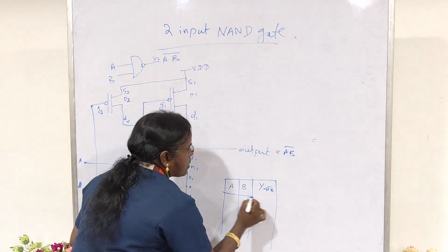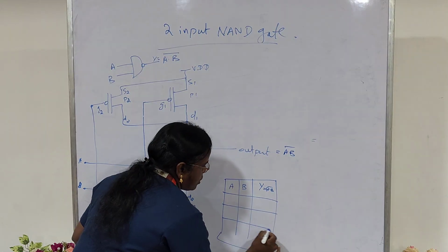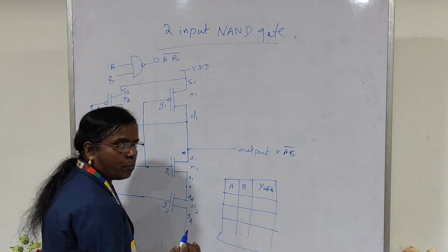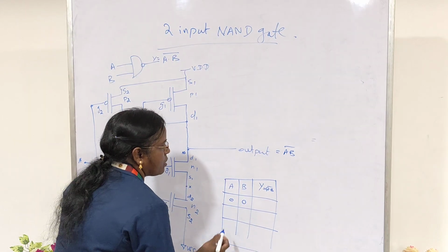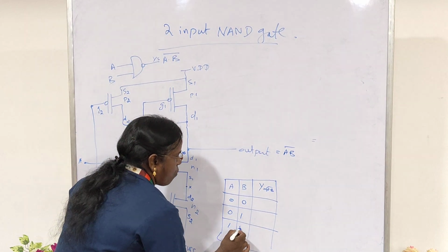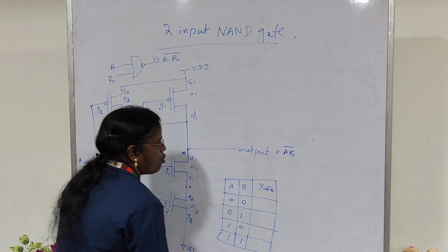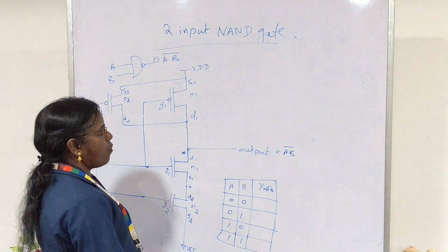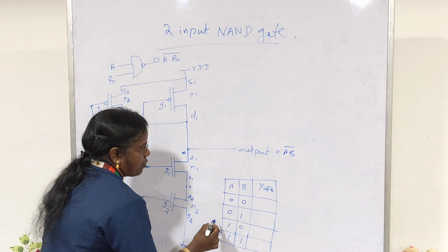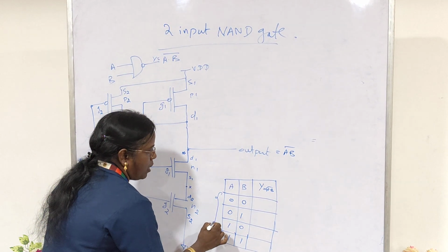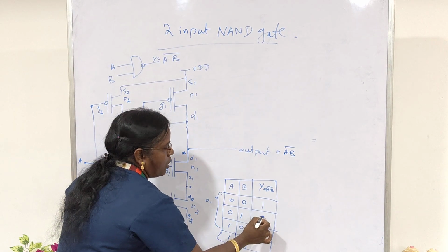Okay, now how the circuit is functioning based on the function table or truth table, we can consider we have two input variables A and B. So we can have the four possible input conditions 0 0, 0 1, 1 0 and then 1 1, right? So these are the possible values of A and B variables. How we can interpret the functionality of this NAND gate means, if any one input is 0 in the input condition, right, the output will be 1.